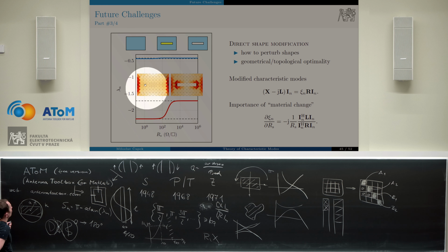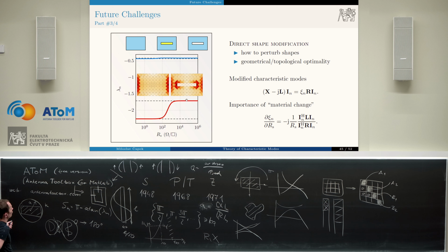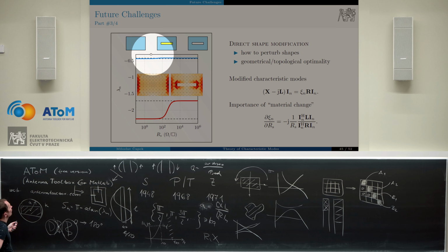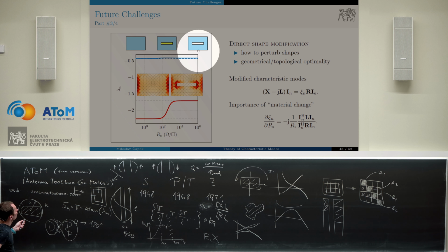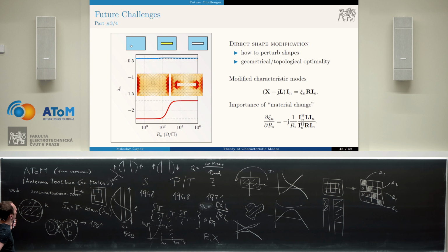So on the left, we have the rectangular plate. On the right, we have the plate with a slot. So the first eigennumber is not changed, the second is changed. And here, actually, to realize this, you would evaluate the decomposition for the shape here and for the shape here. But what I'm showing on this slide is that what happens if you cut the slot in the middle and how the eigennumber is changed can be somehow realized from the evaluation of this shape already.